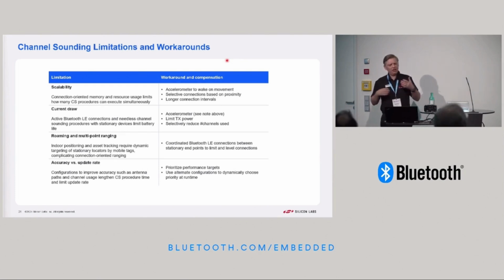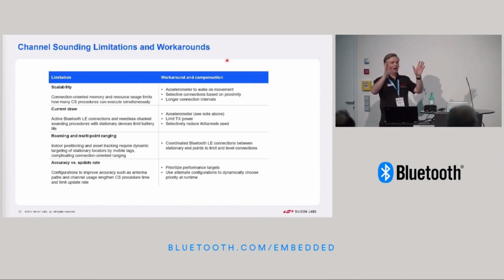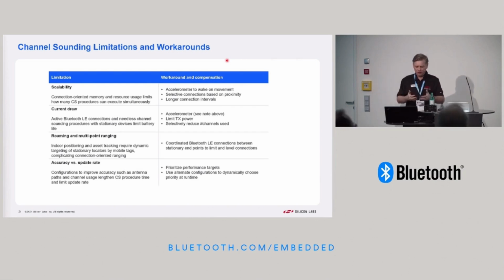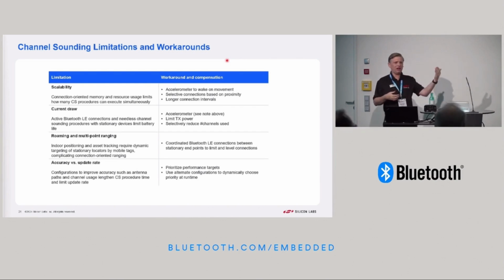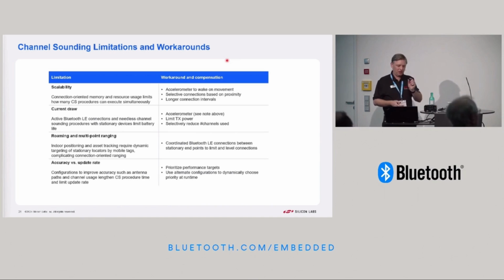Another limitation that we've talked about with the hospital floor presumes that you have multiple access points across a very wide space, and a given asset is not going to be connected to every access point at the same time. So effectively, your access points just have to be smart enough to selectively communicate only with devices that they know are in a certain proximity, either using RSSI or using channel sounding as a temporary solution until motion is no longer detected, for instance.